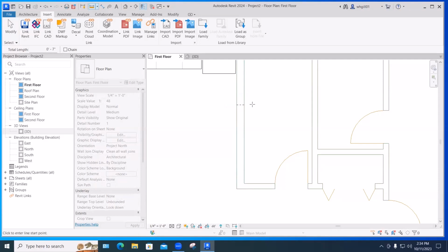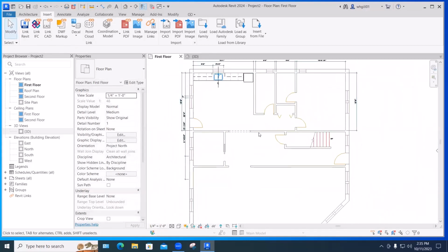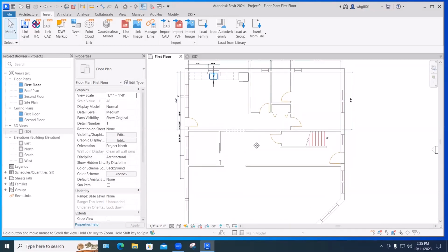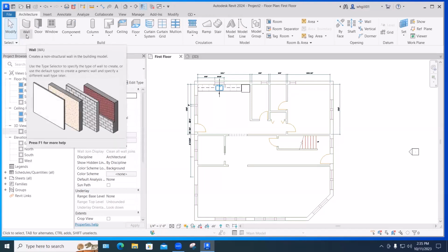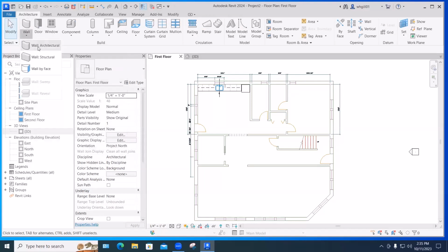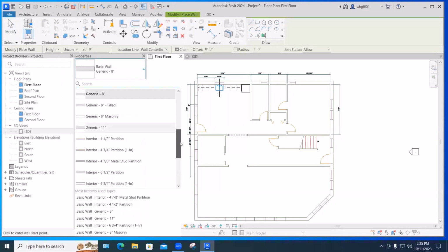And that's typical because you've got large pipes and stuff in there that just need a larger wall. And then lastly, the outside wall we'll measure: an even foot. So assuming that there are no others, I want a 5-inch generic wall, a 7-inch generic wall, and a 12-inch generic wall. Let's see what we got. We'll just draw those perimeter walls to start with. And I don't have a generic 12-inch wall.